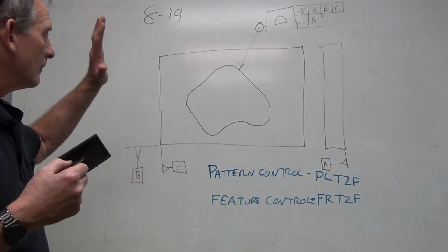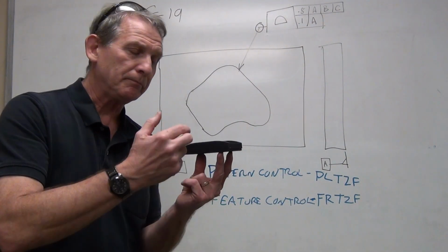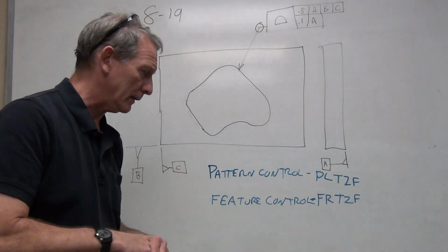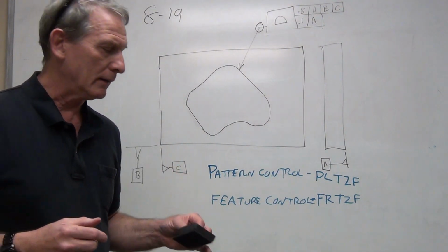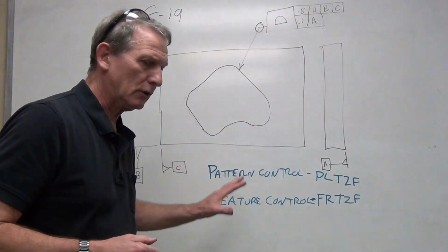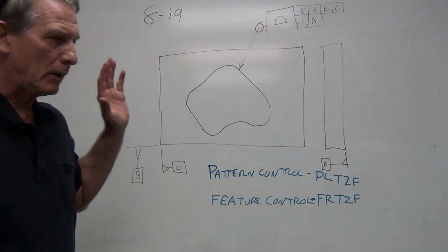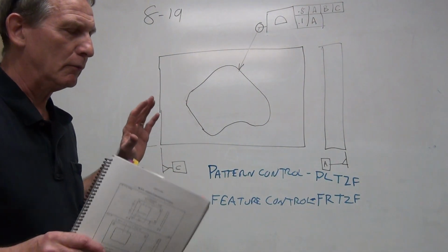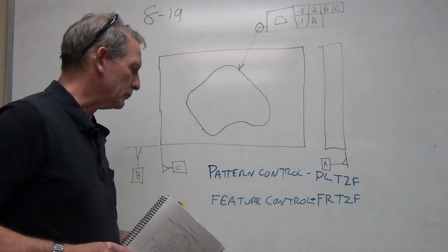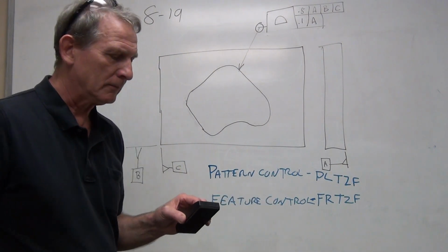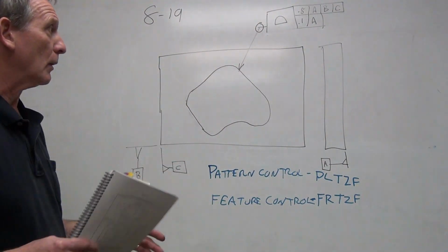So that means that this block, if I am touching all of these surfaces all at once, as I must, the part is fully constrained. It can't translate in any direction. It can't rotate in any way and still meet the requirement of touching all those data points. So it's a fully constrained part. Now, not all parts need to be fully constrained, and we'll talk about that a little bit more when we get to position. But anyway, just think of this as a block that is locked in a vise sitting on parallels. It is fully constrained, it's not going anywhere.